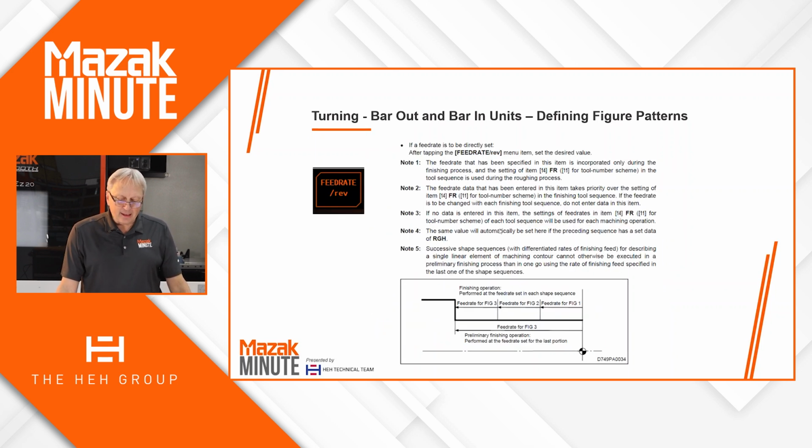If I come down to the next, it is going to be the feed rate per rev. The feed rate per rev, I use a little bit more myself. Tooling vendors have charts that tell me what the tool nose radius is, and then a chart at the top that maybe shows me the micro finish. And if I do the cross section, it would tell me the inches per rev to type in.